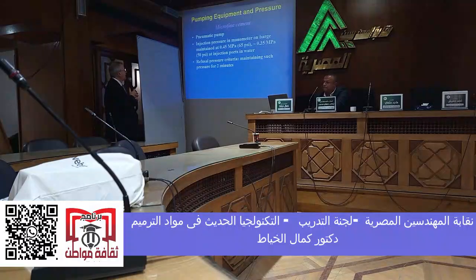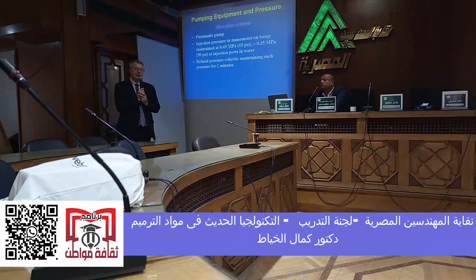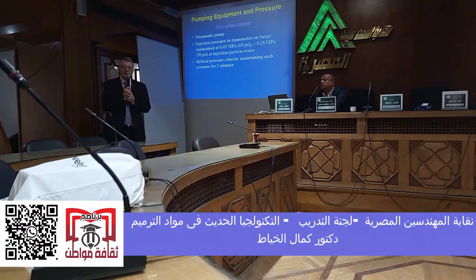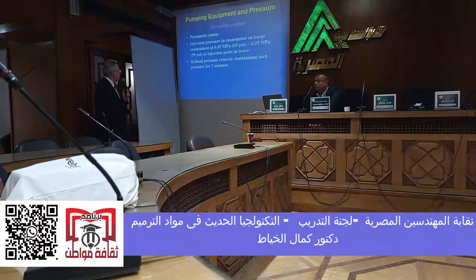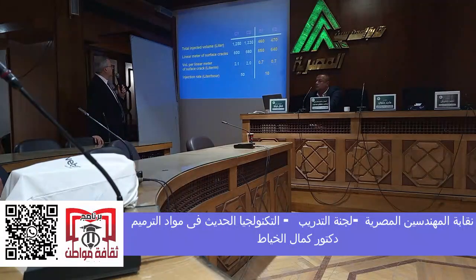Next, for the microfine cement, the injection pressure was a lot less. Instead of 1.5 megapascal, it was 0.35. And this is very important because you have a bridge over it, and this is unreinforced. If you have a lot of pressure, you can elevate it. So 0.35 megapascal, and again, refusal was 2 hours without intake. Next.